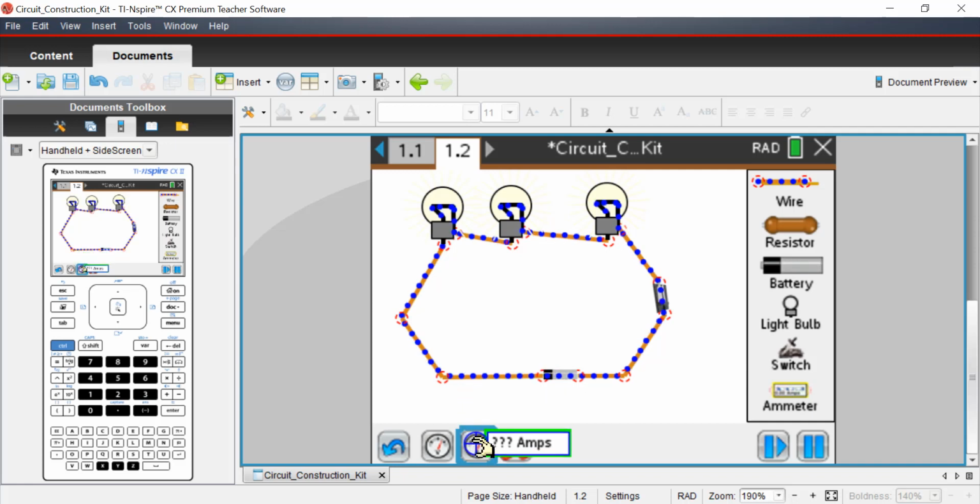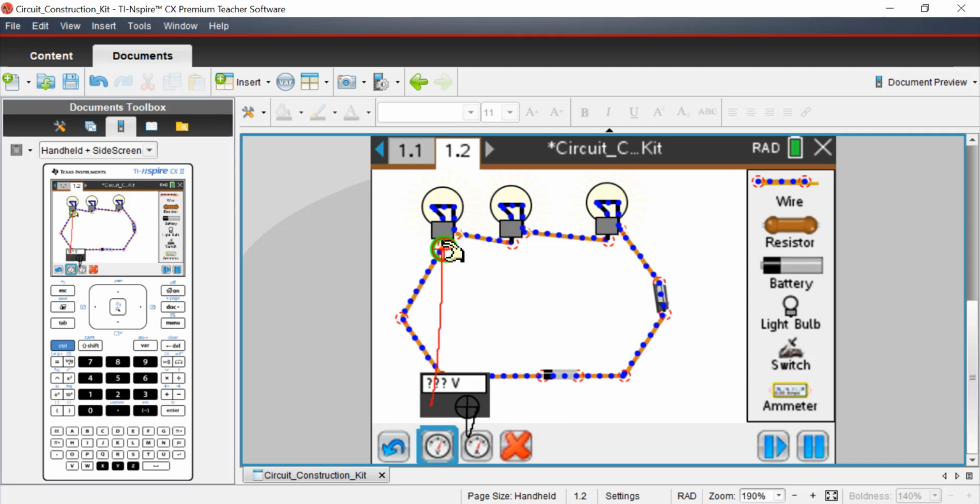It's what I got. And then if we take a look at voltage, voltage across both resistors shouldn't change much. It shouldn't change at all, actually. Yeah, 9 volts. But voltage across a 10 ohm resistor is cut into a fourth. So it's 2.25.